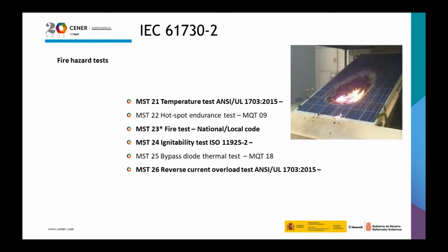The fire hazard tests assess the potential fire hazard due to operation of a PV module or failure of its components. The temperature test is designed to determine the maximum reference temperatures for various parts and materials used to construct the module.